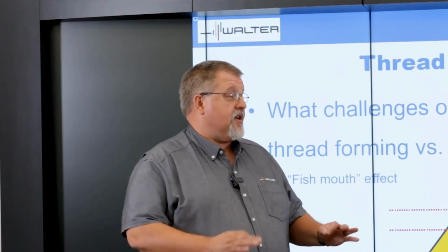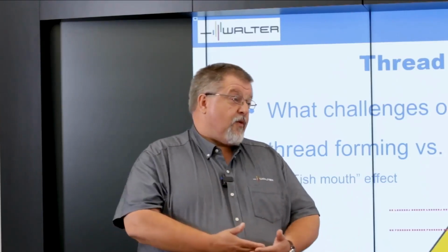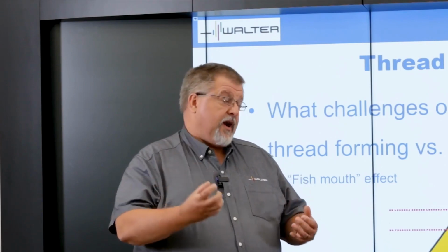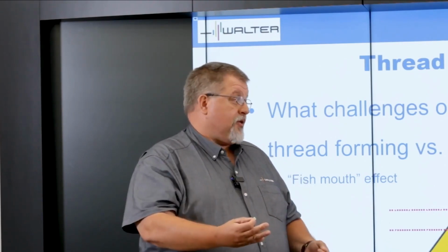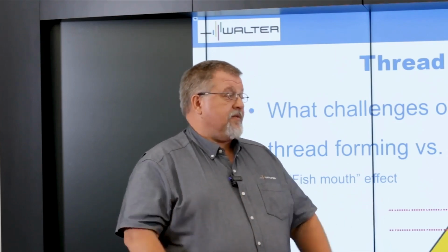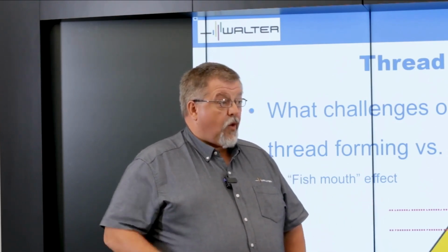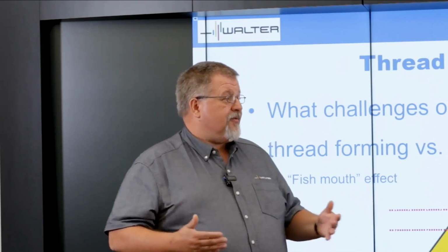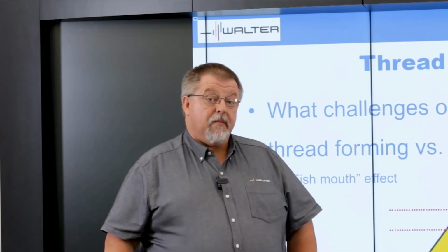That's one of the biggest advantages of thread forming. Yes, we are creating a stronger thread, but we're also creating it faster. And in the process, we're getting an increased tool life out of these tools. Thread formers, in general, can last 4 to 10 times longer than a cut tap.